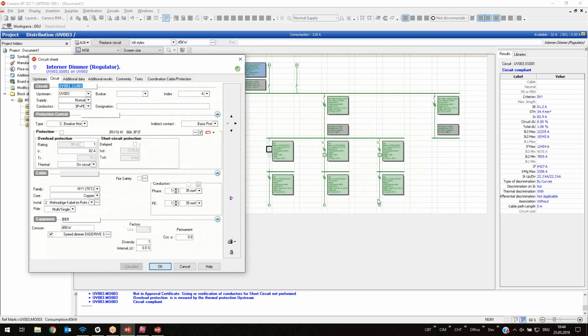So you mean two of them are consumers, and one of them is generating. It becomes a feeder, yes. By the process, these two motors are somehow running the third motor like a generator. Okay. So this means this motor is bringing power back to the bus bar.